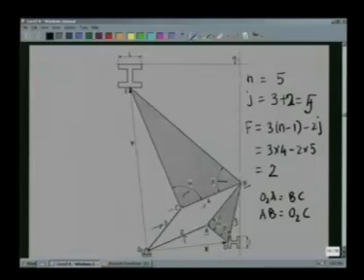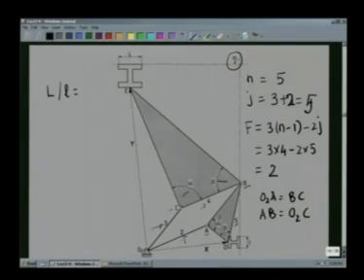For example, here if the point D writes this letter H, then E will write this letter H, but the height of this leg of the H is capital L and here it is small l. Similarly, this H is the normal way, that is vertical, and this H is almost horizontal, that is, it has been rotated through an angle sigma. Our task is, given the link lengths, let us find what is the scale of the reproduction, that is, what is the value of l by L, and what is this change in orientation, that is, what is the angle sigma once we are given the links completely, that is, the link lengths and the angles alpha and beta.